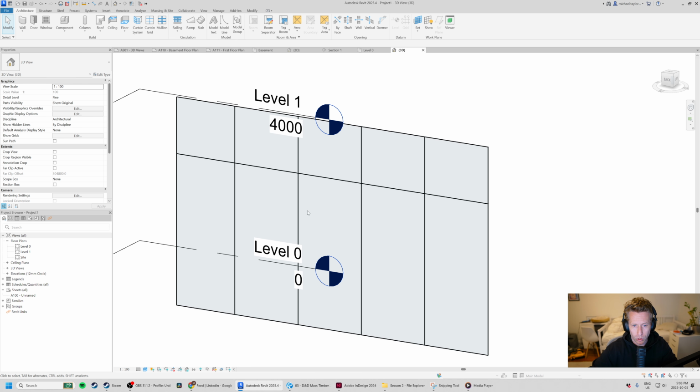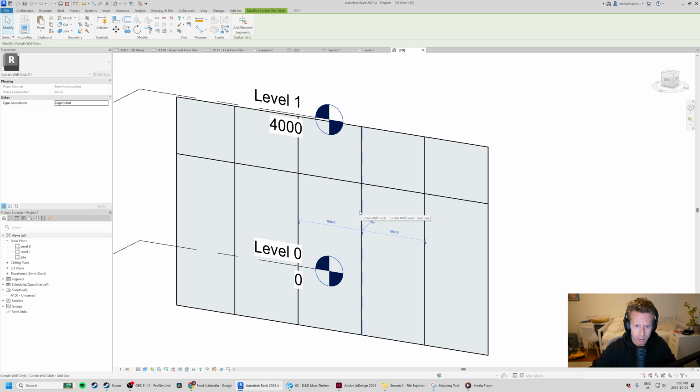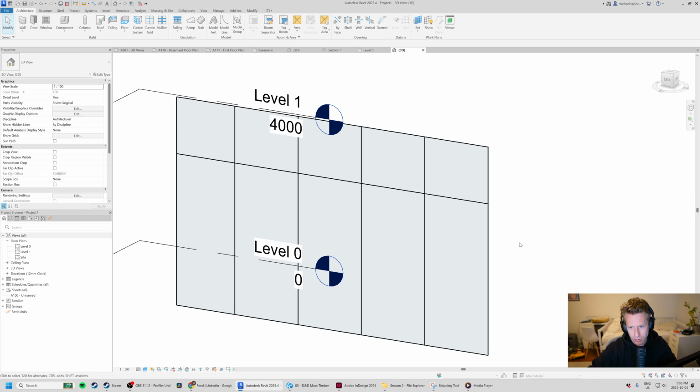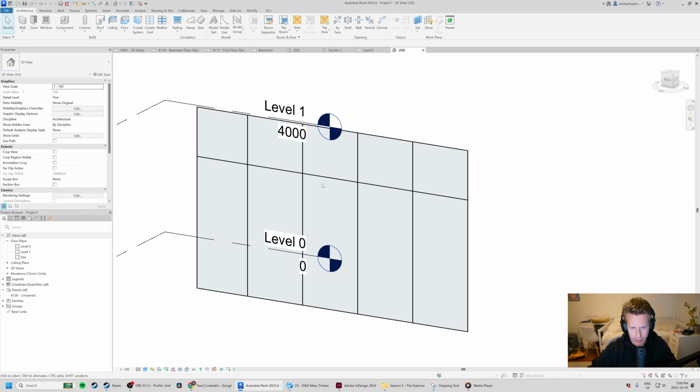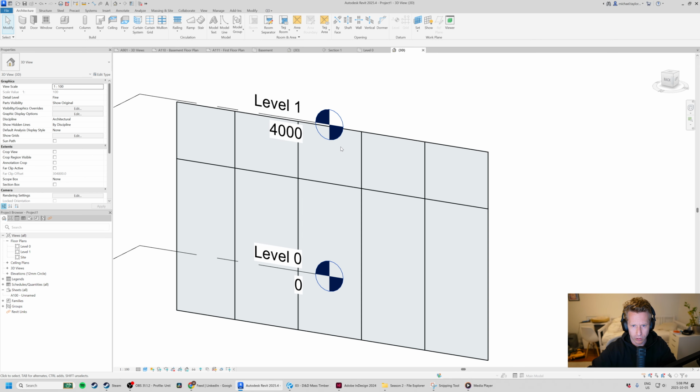If we've got a curtain wall grid that we want to be equal between, say, a 9 meter grid, then this is where our 1500 millimeter module might come into place, right? So 6 units of 1500 would make up a 9 meter grid. So those are the grids. I'll talk a little bit more about those in a bit. I just want to get to the anatomy of each of these pieces here.